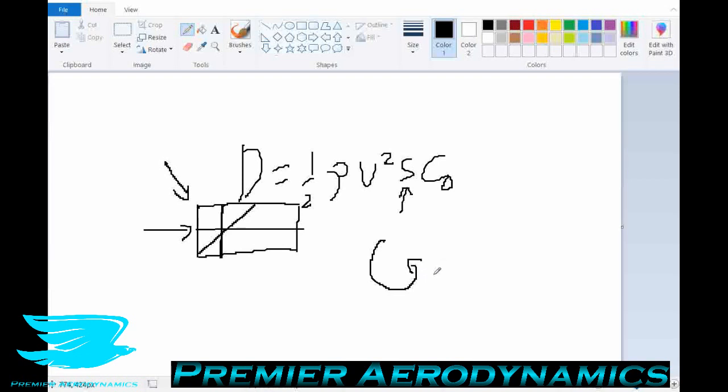So you have big eddies first of all, then they start to break down and they fuel the little eddies that form. Then these little eddies will break down and fuel smaller eddies. Then these small eddies will break down and fuel even smaller eddies until viscosity. And then we just get viscosity and then nothing. That's the energy cascade. You have a lot of energy in the big eddies, then that flows to the next size eddies and down until we get into just viscosity, which then just turns it into heat.